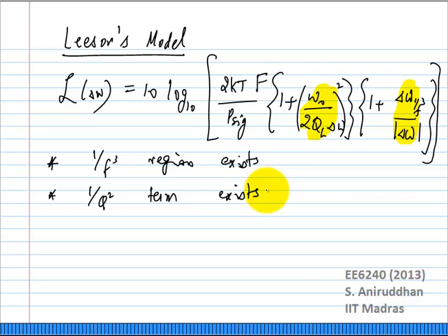If your circuit that you're attaching to this resonator has an input resistance, that will also change the overall Q of the frequency behavior. If you look at the overall frequency behavior, it will not truly represent just the frequency behavior of the tank, but it will include that plus whatever loading happens because of the circuit you are connecting to this.